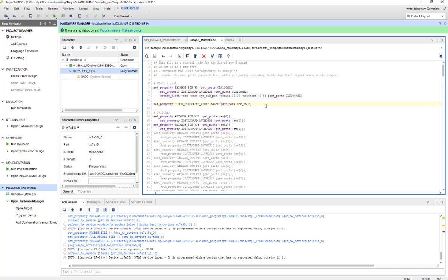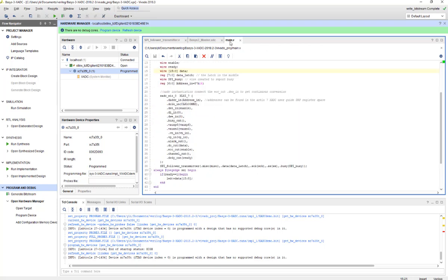So what you should do is put a single line of this into a constraint file, and then the error message will be gone. Okay, so it's basically telling it to disregard that clock pin, just treat it like a data pin or something. So it's going to get rid of the issue. And come back to this one.